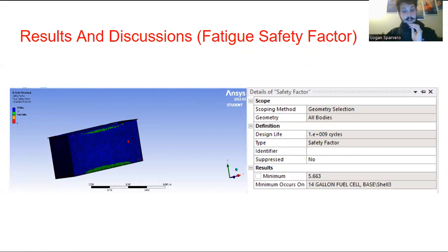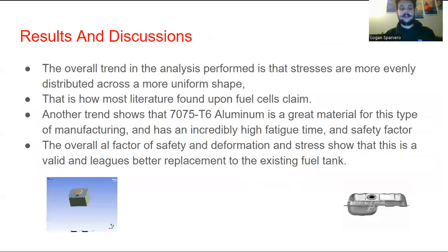Now we're going to talk about the fatigue factor of safety. Same deal. It's not as high as I would like, but it is still 5.663 at the minimum. And it is on those edges while withstanding this force, which is the average force of impact in an accident. So you can see that the fuel cell is extremely strong, and going into discussions, that is mostly because of its shape.